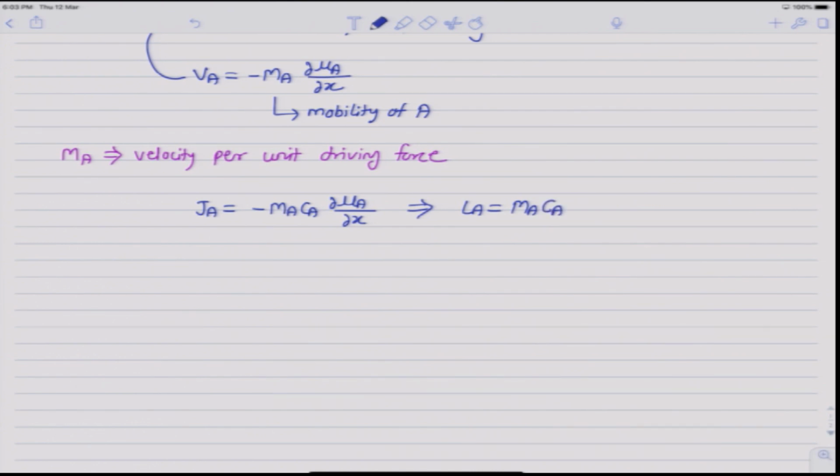So, the atomic mobility or kinetic coefficients, they represent essentially the same quantities, they are related through the concentration Ca. But the mobility is more general term, and mobilities are also used to store the databases for interdiffusivities and diffusivities. And so, let us try to establish the relation between the mobility and the diffusivity terms that we use.